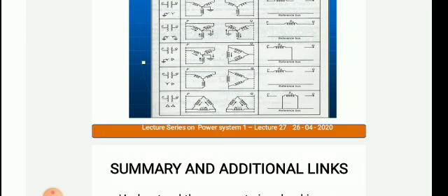Next, delta delta. As both are delta, the shunt switches in both the primary and secondary will be closed and the series switches in both are open.